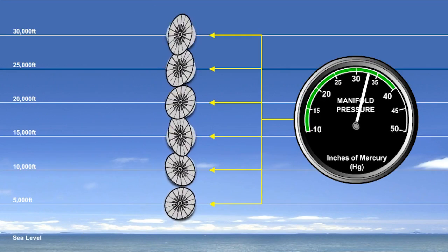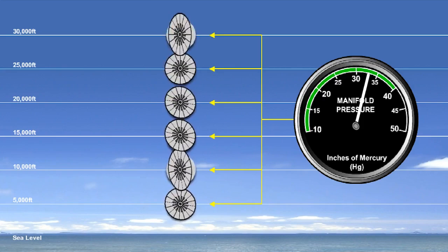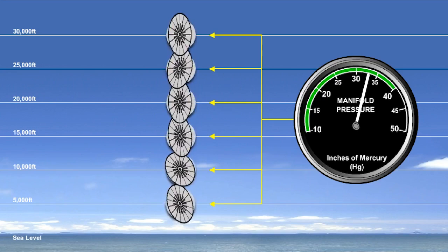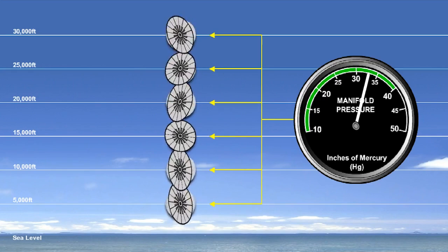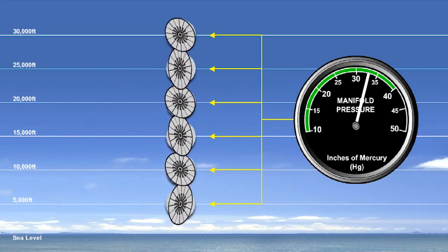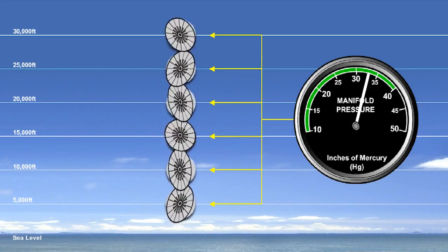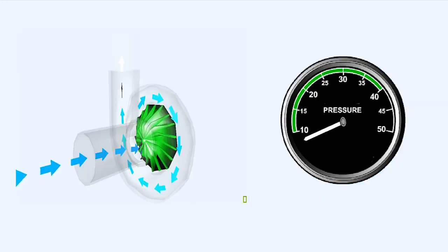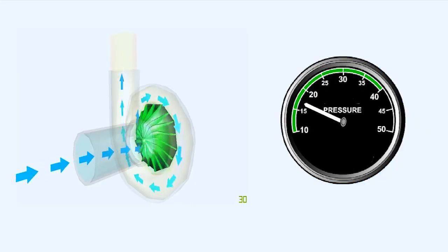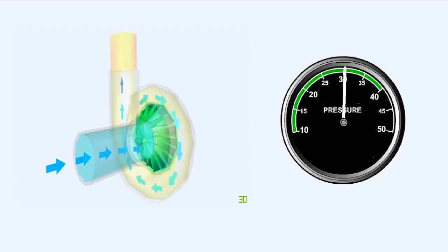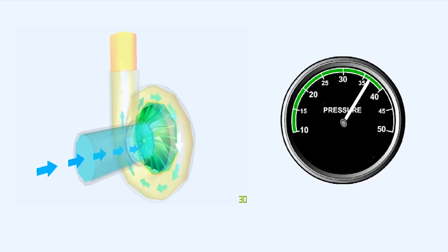For any particular power output, the turbocharger must deliver a constant mass of air to the engine in a given time, and since the density of air decreases with altitude, the impeller rotates faster as the aircraft climbs to compensate for the reduction in density, and so maintains the selected manifold pressure. Some form of control over compressor output must be provided, and this is done by varying the quantity of exhaust gas passing to the turbine to vary its speed and that of the compressor.